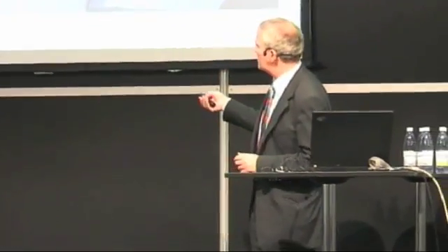Even with such a tool, here we have to reduce the feed rate to roughly 50% of the nominal feed rate. Another option is entering the component at an angle. Normally you have to do a face milling first to enter straight, to have both inserts in touch even when you are entering the bore.